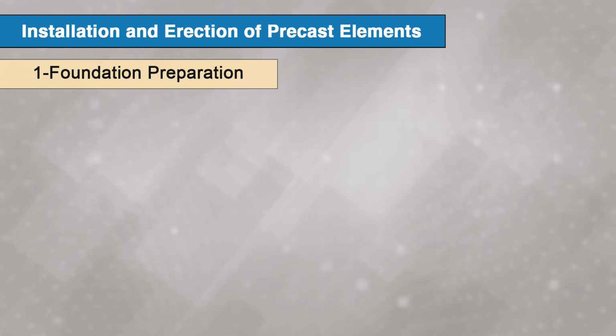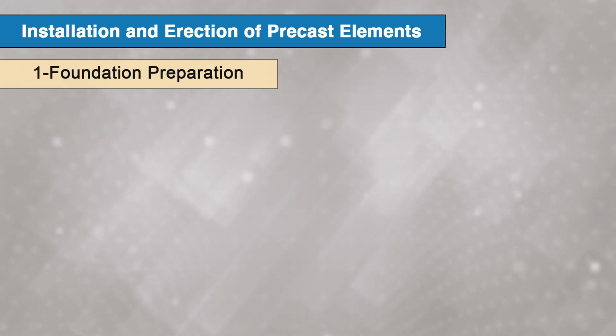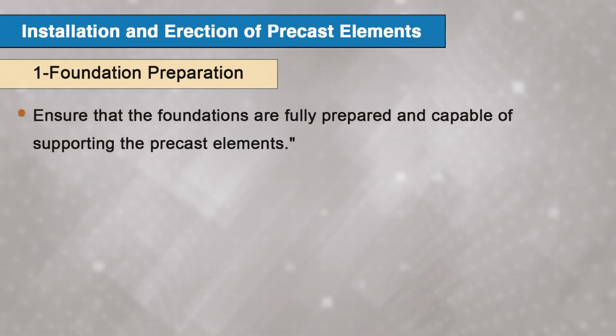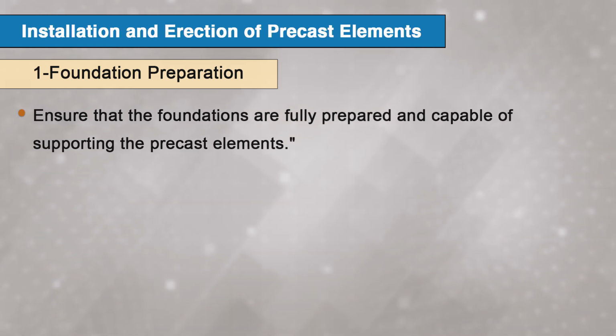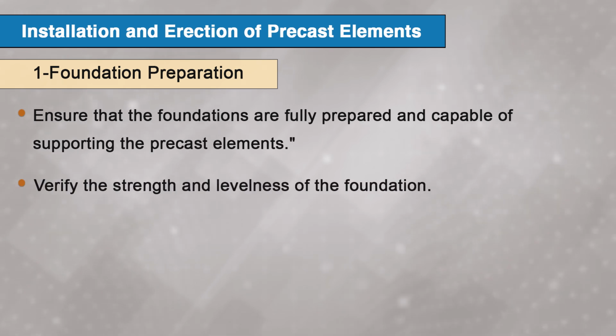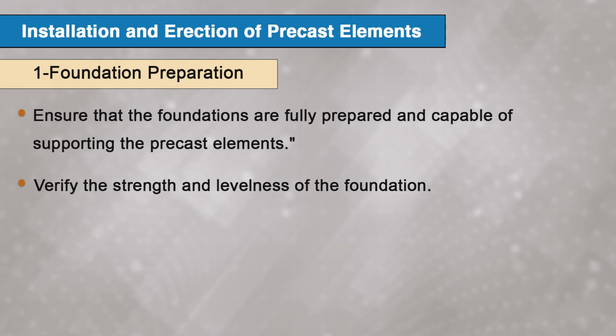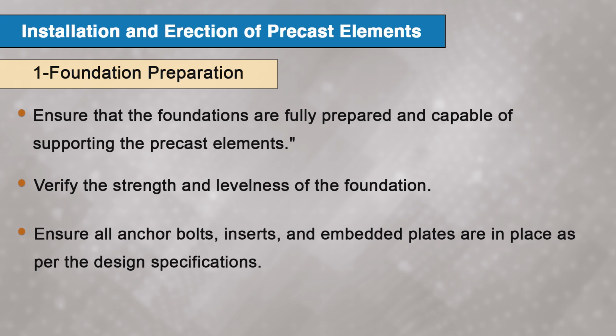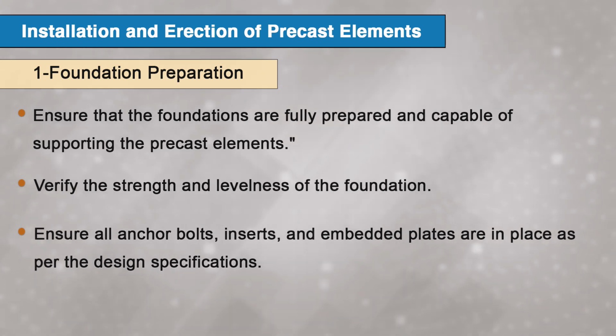Moving on to our next topic, that is installation and erection of precast elements. It is equally an important topic. The first point in this is foundation preparation, whose objective is to ensure that the foundations are fully prepared and capable of supporting the precast elements. The steps involved are: firstly, verify the strength and levelness of the foundation, and ensure all anchor bolts, inserts and embedded plates are in place as per the design specification.